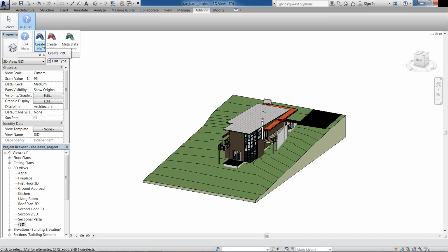You can select and choose families and specify within your catalogs of families, and by using 3D PDF PRC, you can add those into your documentation. You can simplify and list all your families on your regular list of families that you use within your models through your templates. This gives you a list of regular use and simplifies it every time you do a new model.